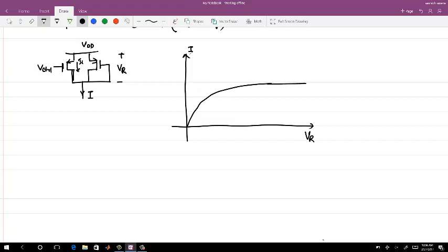So this will be something like this, okay? If you're considering all the square law parts, let me make it in a more ideal fashion, that once it saturates, it actually becomes constant. And this voltage will be your VDD minus V control minus mod VTH. And what is the current in the second transistor? This is I1 and the current through this is I2. So the current I2, as per the square law, will go something like this. This is your I2.